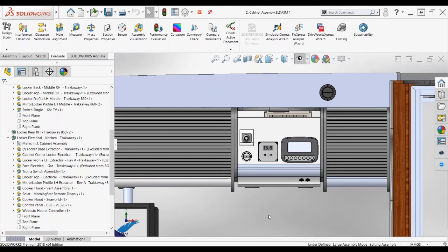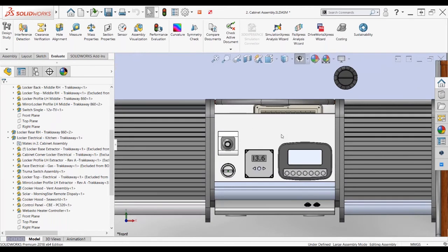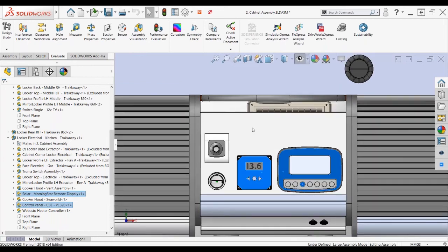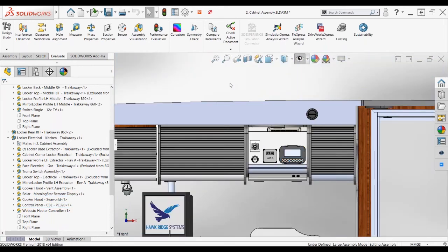So there's a hotkey for that as well. It is the T button. So if you tap T, that will toggle that on and off, making your first click blank graphic space. So that's also really nice if you want to kind of unselect things. So if I'm sitting in here and I don't want to select something, now I don't have to zoom out and click in blank graphic space or hit the escape button. I can just click through any of my components.